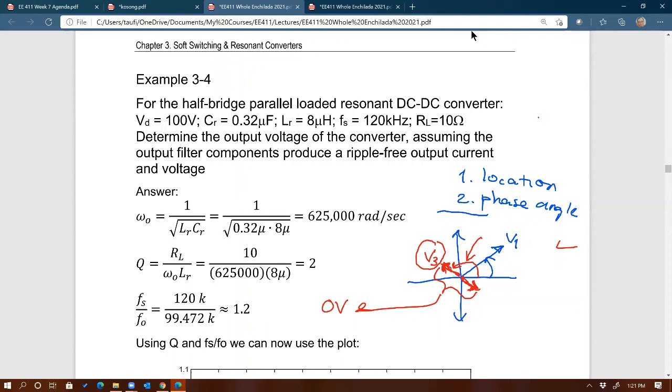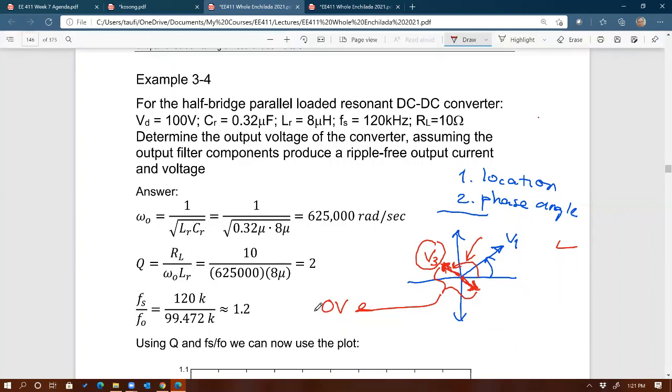Expensive, yeah. But it exists. These harmonic filters, they call it active harmonic filter. They exist, and they're very expensive, of course. Fancy injection filters, right? But it's clever. You just look for the location of the harmonics and add 180 degrees to cancel, right? Zero.